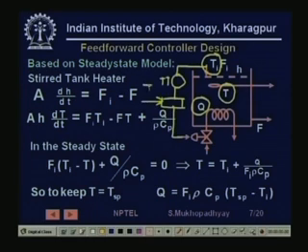Here we give the set point. So, we are sensing the disturbance, and this is my feed forward controller, and I am applying this input u. Okay. So, if that be so, then what should be my control law for Q such that the left hand side of this equation will be 0, which means that the temperature will not increase.